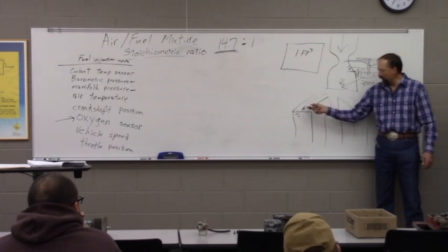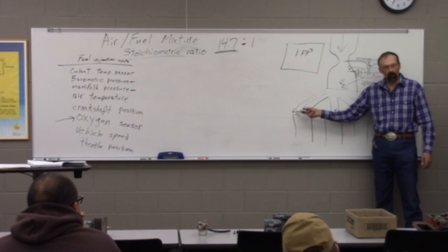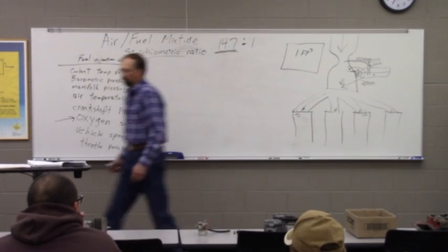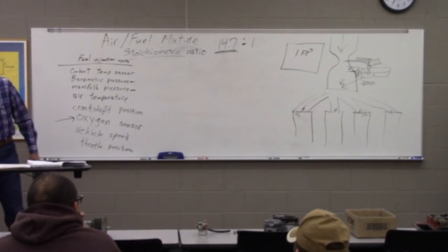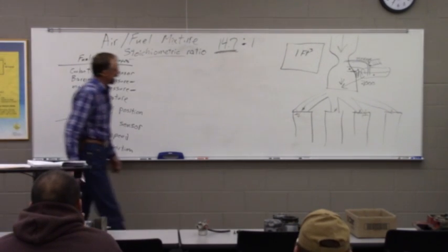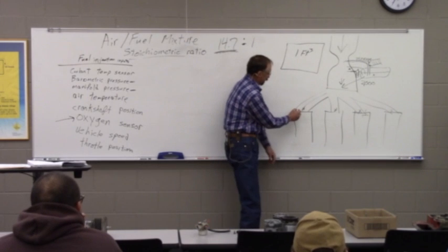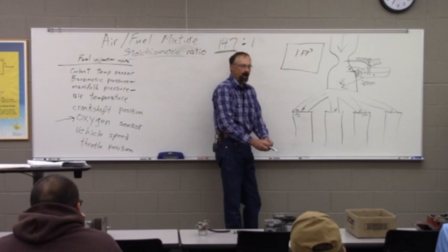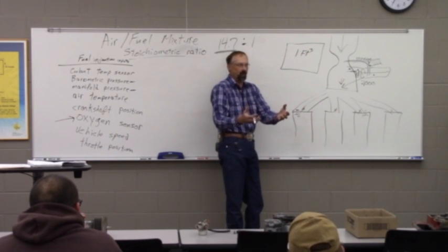because when you fire this injector while this valve is shut, you wind up puddling a little bit of liquid fuel in the, these are some of my reminders to help me try and stay on time, fellas, but you wind up puddling some liquid fuel over here because there's no airflow moving and we're not atomizing that liquid into vapor fuel.